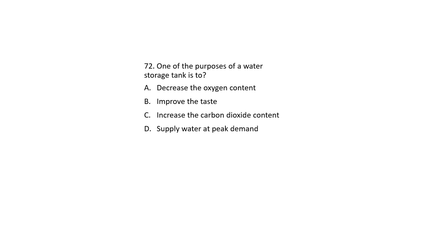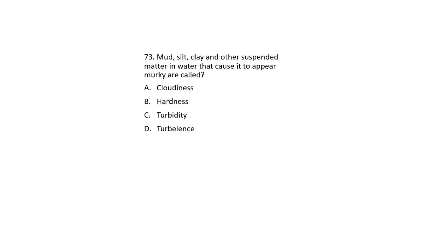One of the purposes of a water storage tank is to increase the oxygen content, improve the taste, increase the carbon dioxide content, or supply water at peak demand. And you are supplying water at peak demand. Mud, silt, clay, and other suspended matter in water that cause it to appear murky are called cloudiness, hardness, turbidity, or turbulence. Answer C, turbidity.